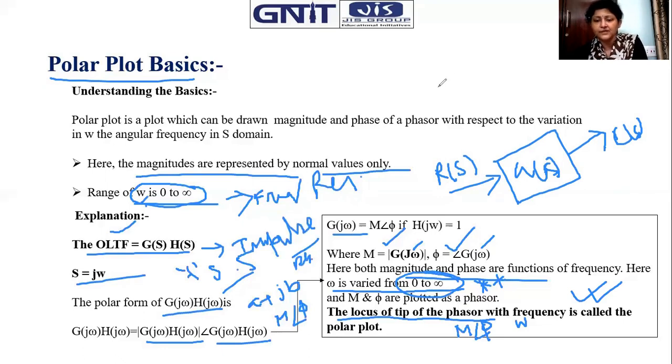We are going towards impulse response. Why? Because R(s) we set to unity. That means it is nothing but the impulse response. R(s) is unity because the delta function, the Dirac function, having the Laplace transformation, we are getting unity. So if we feed that input inside the system with R(s) equals unity, we get G(s) equals C(s). So the output or the response of the system is directly equal to G(s). That's why we are dealing with the unit impulse as the input, the output is C(s), and that equals basically G(s). So we will handle only G(s) in that case.